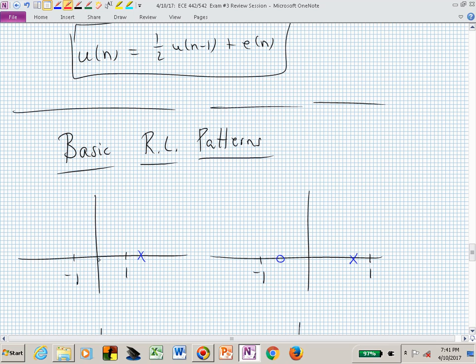If you look at any point here to the left of that pole, they are going to see an odd number of poles and zeros. And as I crank up the gain K, I can move my closed loop poles from some pole that's to the right of 1 and move it all the way to minus infinity. Is it possible to stabilize this closed loop system for some range of K?